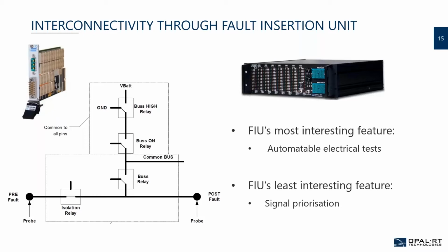This usually is to validate all the cases that hopefully will never happen in the aircraft, but sadly may happen once in a while. And we want to ensure, obviously, that the controller won't go haywire and drop into safe mode and stop the engine, for example. So that's part of the game to be able to test.